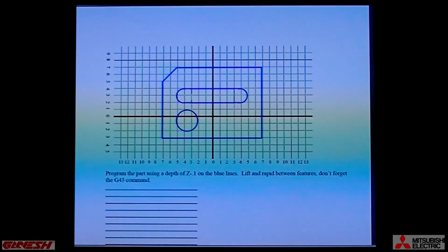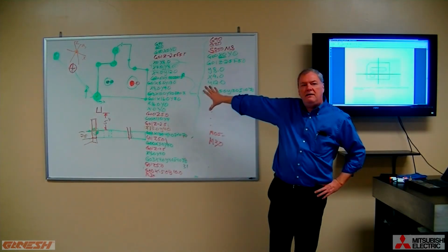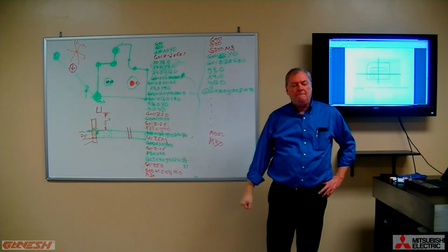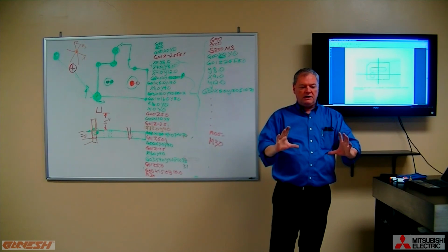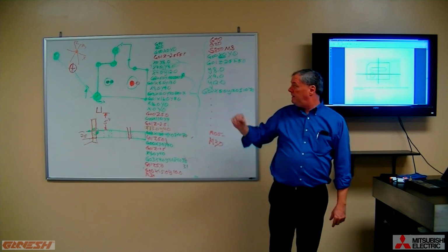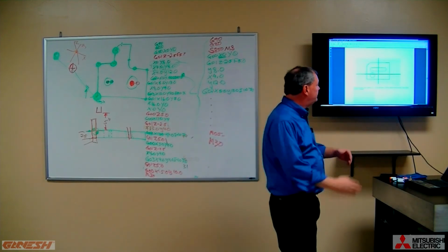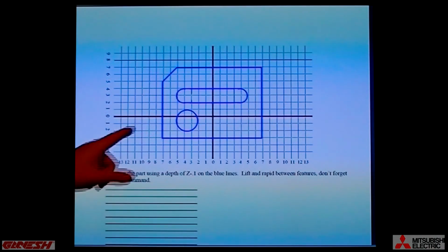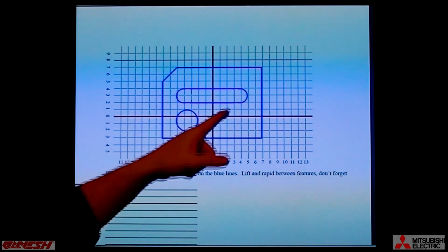So please make a proper program of this part with the addition of the Z-axis moves as we have demonstrated here with this program. So go at it the easy way. First get all your X and Y locations, and then start formatting it with G01s, G00s, then add your Z values. You've got a full 180 degree circle here, 180 circle there.